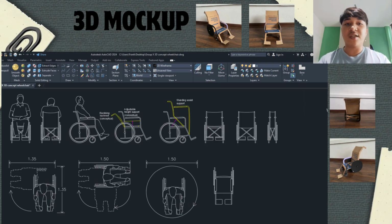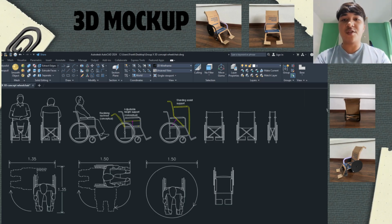The third modification is the standing assist support, highlighted at the front of the wheelchair. The structure consists of a vertical support frame and an upper grab bar position at chest level. The standing assist support is designed to help users transition from a seated position into a semi-standing posture. Rather than enabling full standing, it reduces lower limb load and improves balance, allowing elderly users to perform daily activities with greater confidence. The highlighted lines indicate the load path and user interaction points.